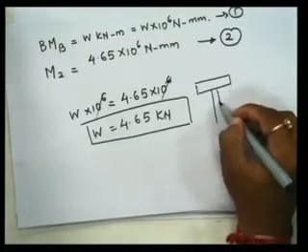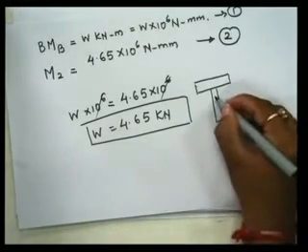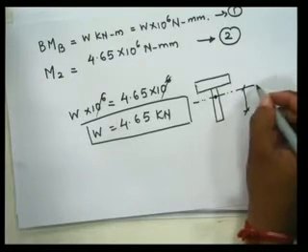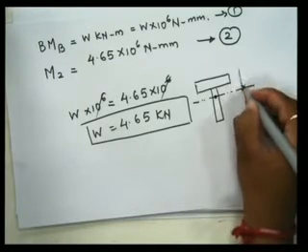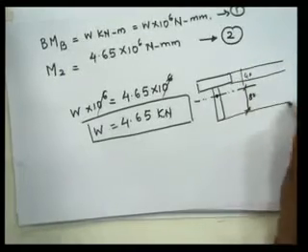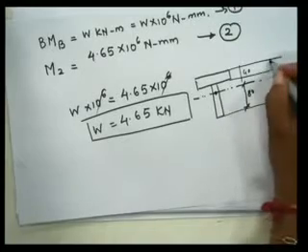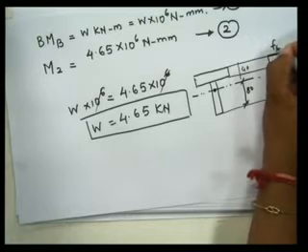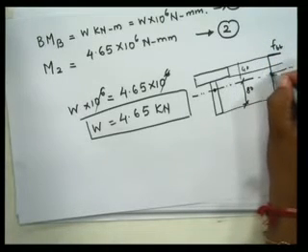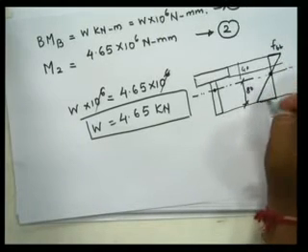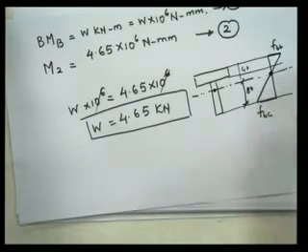right? It is a T shape like this, right? This is our CG point, so I can show this as the neutral axis. This is 80 mm, this is 40 mm. Okay, we can extend these lines as well as the neutral axis. We'll draw a vertical line, then tension will be at top, so I can show FBT. Over here at the neutral axis, no load, 0, then compression, FBC. So this is our final diagram.